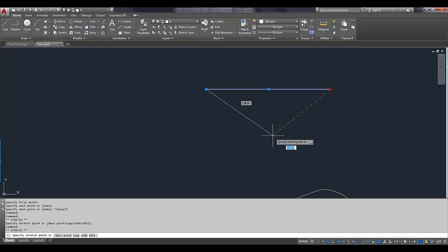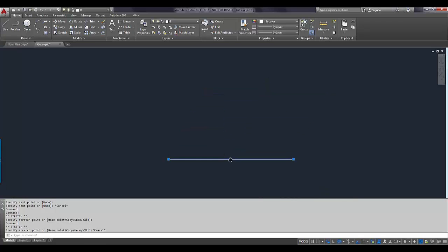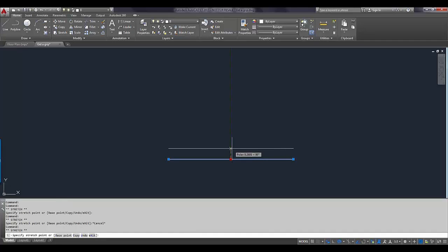But one nice thing, depending on what you're doing, is I'm going to make a copy of this line, and it's going to have the exact same spacing between each copy. It automatically creates an array for you by holding down the Control key. So I'm going to go into copy mode. So let's go about that far.